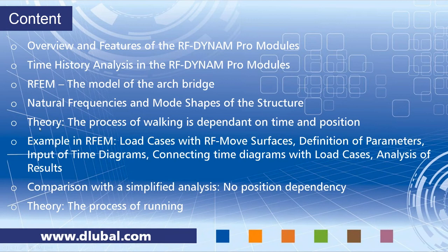Then we go back to the PowerPoint and we will have a look into theory. So how is the process of walking defined? And, as I already said, we want to consider it as time and position dependent. So we study this then all in RFEM, so we apply all the theory on the example. We will define load cases with another add-on module which is called RF Move Surfaces. So this is just an easy tool to create load cases. You can do this manually also, but it is a bit quicker using this add-on module.